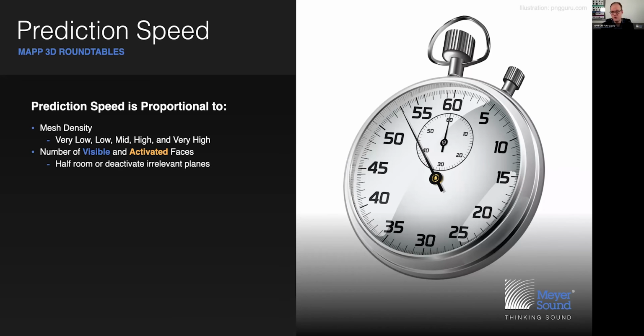What we tend to do for larger rooms is that we prepare our listening planes in such a way that if we're dealing with symmetry, we can only work on half of the room, and then we mirror everything upon conclusion and complete the room. So by working with only half of the room, you greatly reduce the number of activated faces.